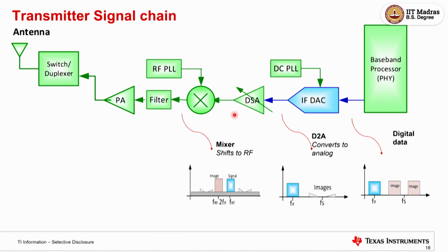So we saw one way of doing different mixing is if you do cos and cos and sine and sine. We said cos A cos B plus sine A sine B, and I can get only one sided information. For that, I need one more chain here. We'll see that in a later part. That is the evolution of architecture. This is the simple legacy architecture that I took. Simply, if you want to mix, you just do a multiplier, and it will create two components. This is an unwanted component. I want to send only this in air. I don't want this in air, but this has come right now.